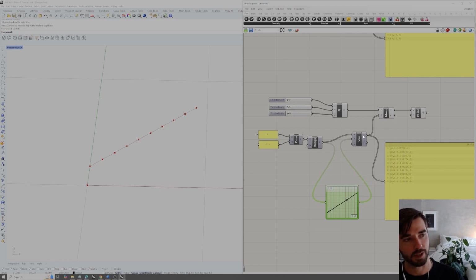And then it's giving us output values for the y value, and then it's outputting this vector. So each of these vectors from 0 to 9 are giving us certain values based on this equation, which are plugged into the move. Each one of those points are moved in space, and then the polyline is drawn accordingly.